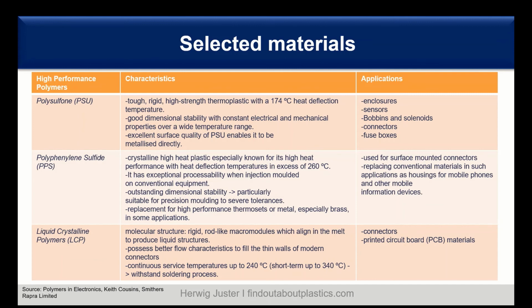Then we have liquid crystal polymers, LCP. There we have the special molecular structure. So here you have to imagine you have rigid rod-like macromolecules which align in the melt. So you have liquid crystalline structures which have a self-reinforcing effect. You can imagine similar to glass fibers.